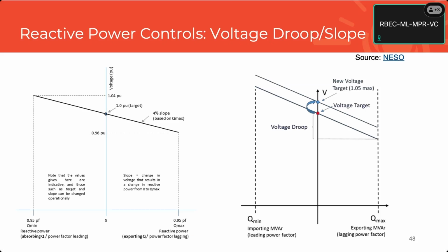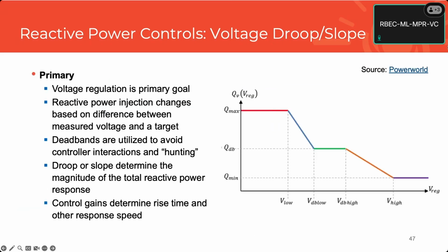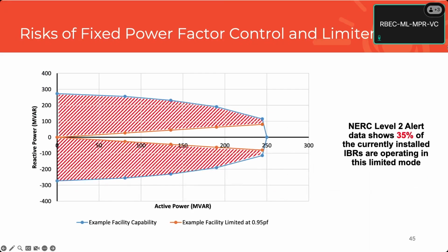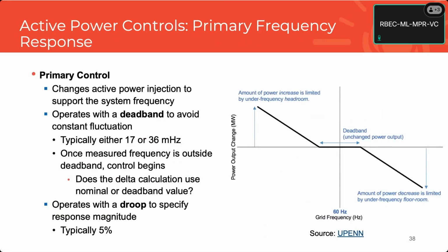And the pushing around aspect of it will get worse as the system's strength reduces as well. Like a very strong system, very firm voltage. If I'm a 100 megawatt wind farm, I'm probably not cranking the voltage of the system around too hard. If the system strength is strong. If it's weak, then I can move the voltage pretty substantially, which means I'm giving everyone else a different measurement to go on. So if you have a really weak grid, you probably want a less severe slope, like a higher percentage of slope, less response, or maybe a larger deadband.